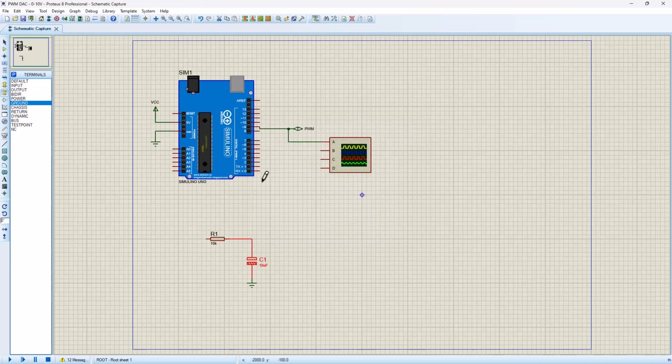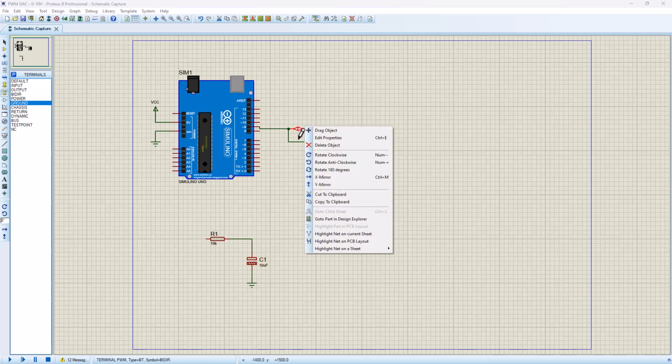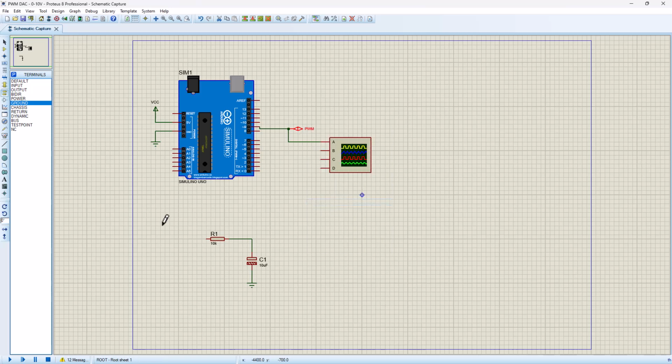So we're going to make sure we don't have any high frequency component, but you can decide which value you want to use for your particular design requirement. So I'm going to just paste this. Great. Now what I've done here is I've included a voltmeter across my RC output, right? And the output is connected to channel C and the input is obviously from the PWM.